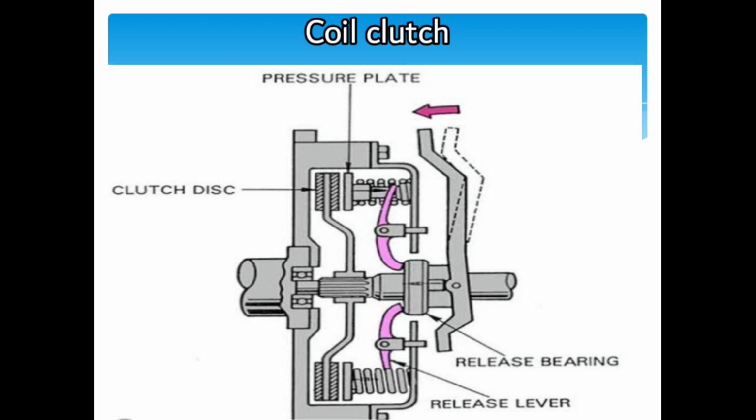A clutch coil is a unit consisting of many windings of wire fastened to the front of the air conditioning compressor. When current is applied, a magnetic field is set up that pulls the armature into the rotor to engage the clutch. This is also known as the clutch field.